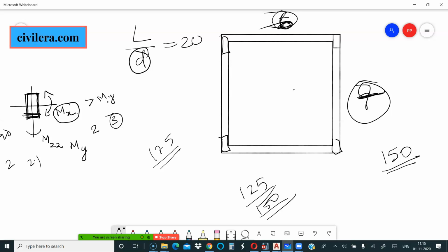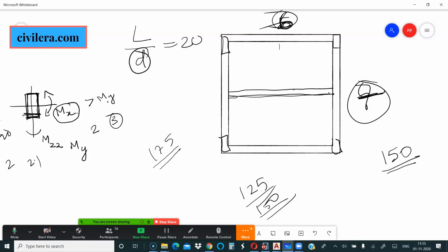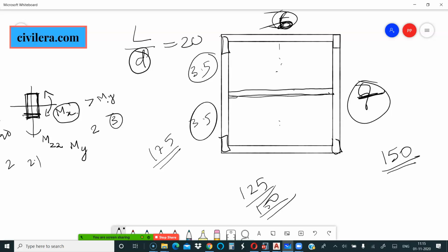Now the question is, will you give the beam in this direction or in this direction or both? I would obviously go with the shorter span. 6 meter is less than 7 meter. So if architecture is okay and the client is okay, then I would give the beam in the 6 meter direction. This converted my slab into two smaller slabs of 3.5 meter. Now this 3.5 meter slab is a continuous slab as well, and I don't think I will need anything more than 120 mm, or even 100 millimeter may be fine, maybe 125 or 120 based on your practice.